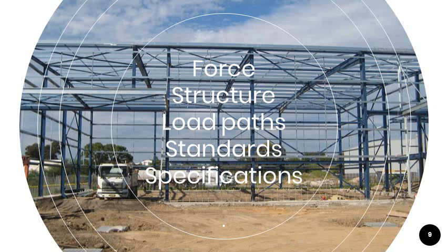Our domestic shed has been designed from roof to footings by establishing forces which act on the structure. The structure is designed to withstand these forces and carry its own weight and varying imposed loads. The forces are transmitted down a path of beams, columns, and walls to the footings as loads. Loads are calculated using equations and Australian standards, and manuals and manufacturers' specifications assist in selecting the appropriate steel members.